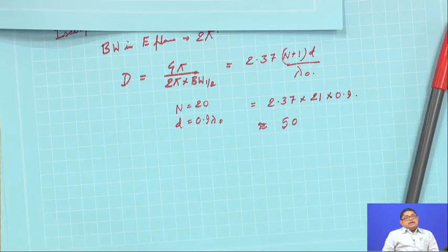So, not bad. That is why in an array antenna the main contribution comes from the array factor, so you can put any antenna. Obviously a dipole will be preferred over an isotropic radiator in the sense of power handling capability and other things. Any type of practical antenna will do. We will see later that in real life the antennas do get protruded. Instead, if the array is on a ground plane and open ended waveguides are flush to that ground plane, that is much preferred, because then only one front surface of the array antenna shows.